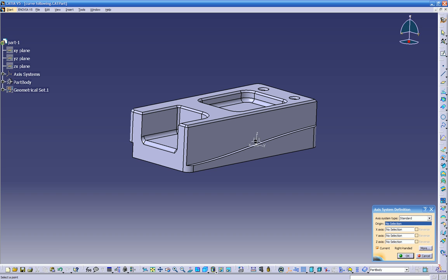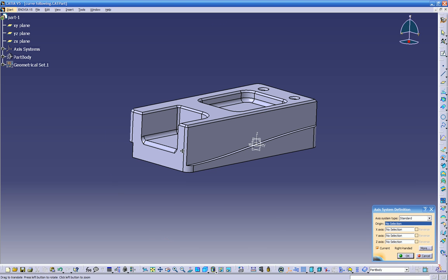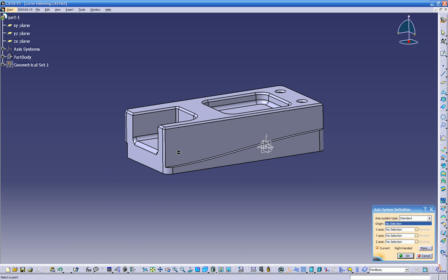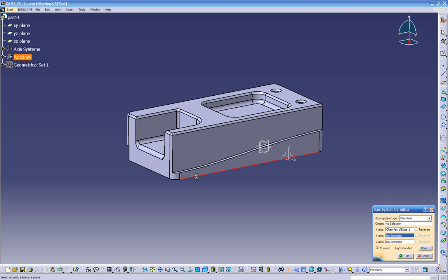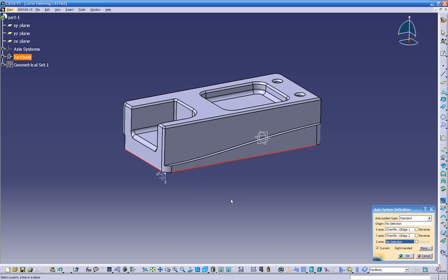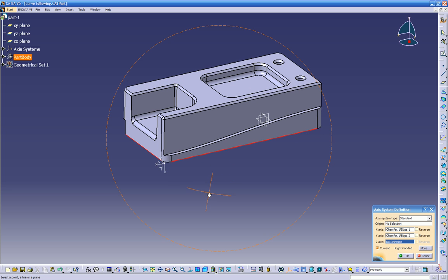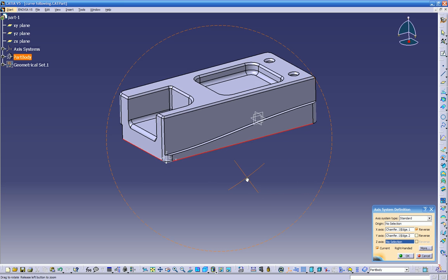And this XY0 are those planes right here. See, I just turned them all on. So automatically it defaults to the XY0, but if we want to move it over here, we just click X axis along this line and X along this line. But now it's backwards, so we got Y the way we want it. X and Z are backwards, so we can go back on X and click reverse, and that looks much better right there.